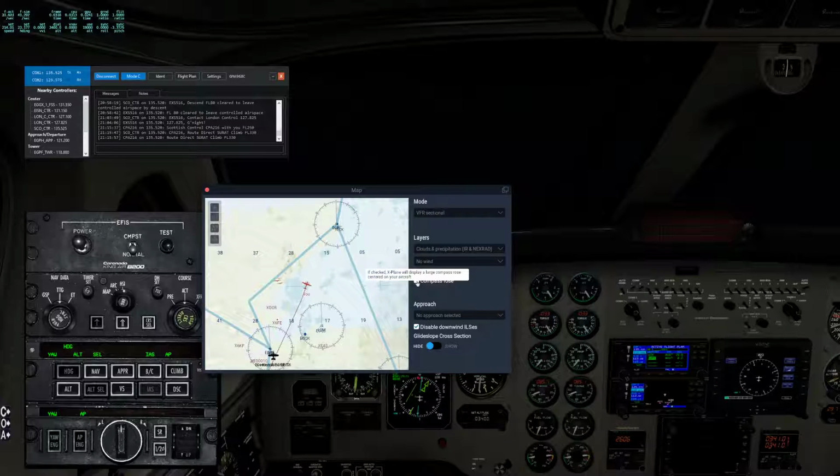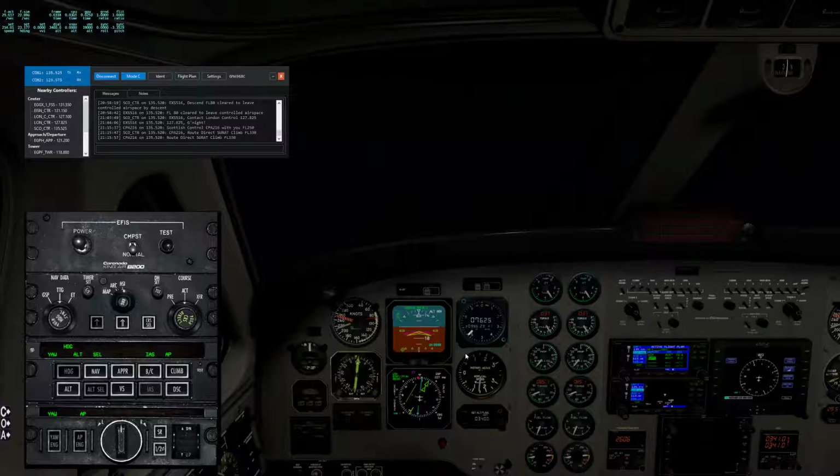As it turns out, I'm now actually in autopilot heading mode, by the way, and I'm kind of tracking by eye using the course deviation bar to see if we can get it to come in about 9 miles out. I'm looking at the distance and seeing how much the bar is starting to move. Well, it's not really moving yet. I'm looking at the X-Plane map and just guessing. As it turns out, the heading we're on is not far off being correct for that initial approach fix.